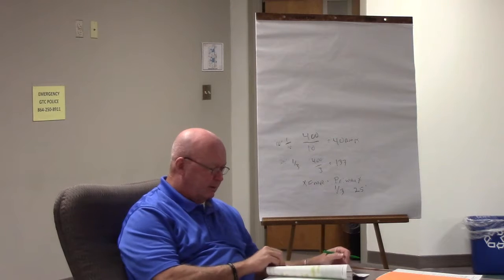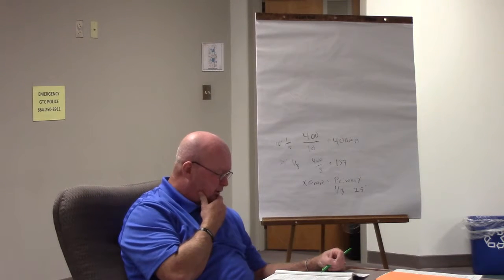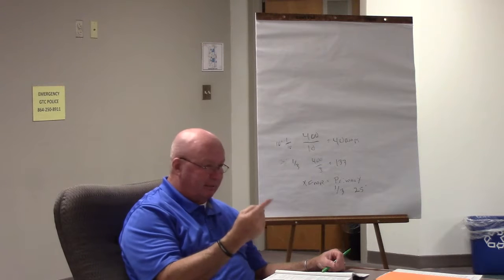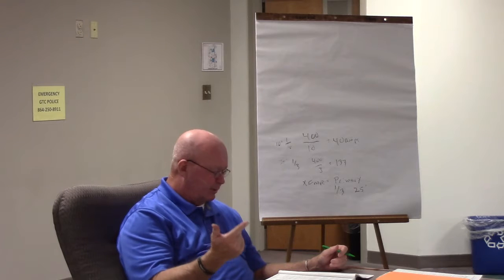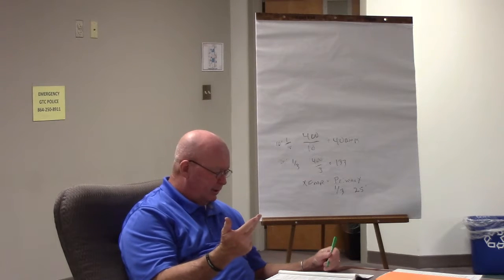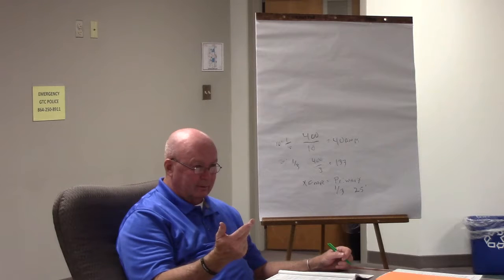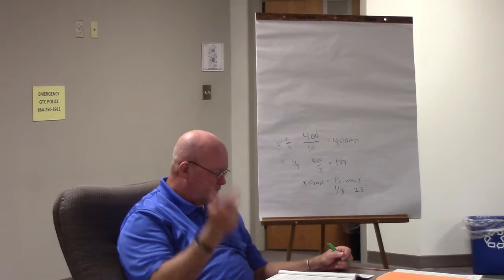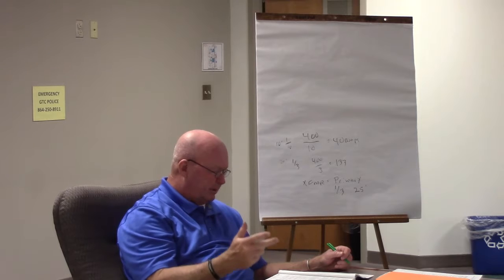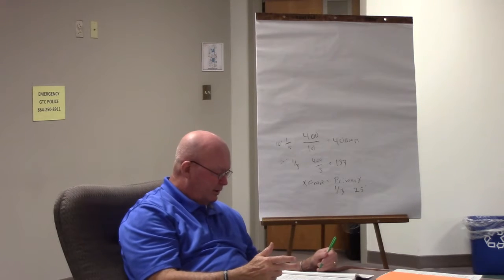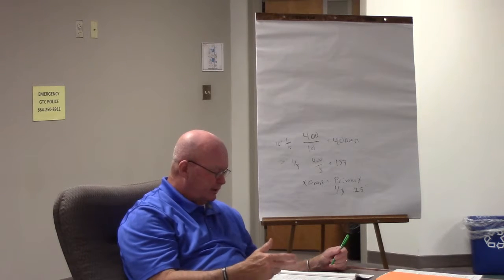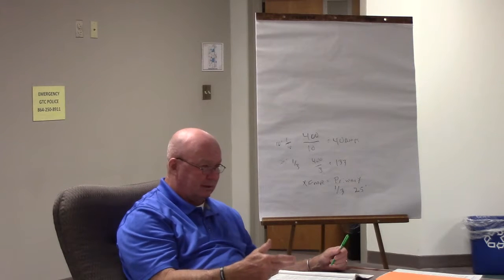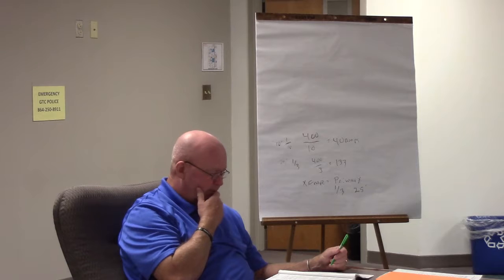We see here that there's some bullet points there. First one, no different than what we've been talking about. It's got what? Got to be what? Protected. Conduit. Number 2, no different. Terminating where? Single breaker. Yeah, single breaker. Okay. Additional loads must be supplied from the breaker set of fuses. All right. Number 3, the overcurrent device for the conductors is an integral part of the disconnecting means or is located immediately adjacent to the disconnecting means. Kind of makes sense, doesn't it?